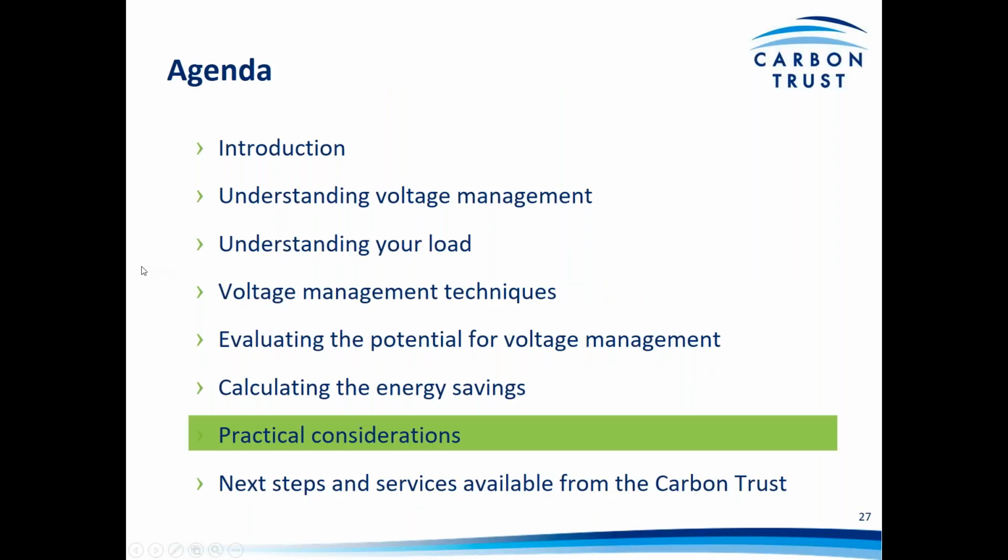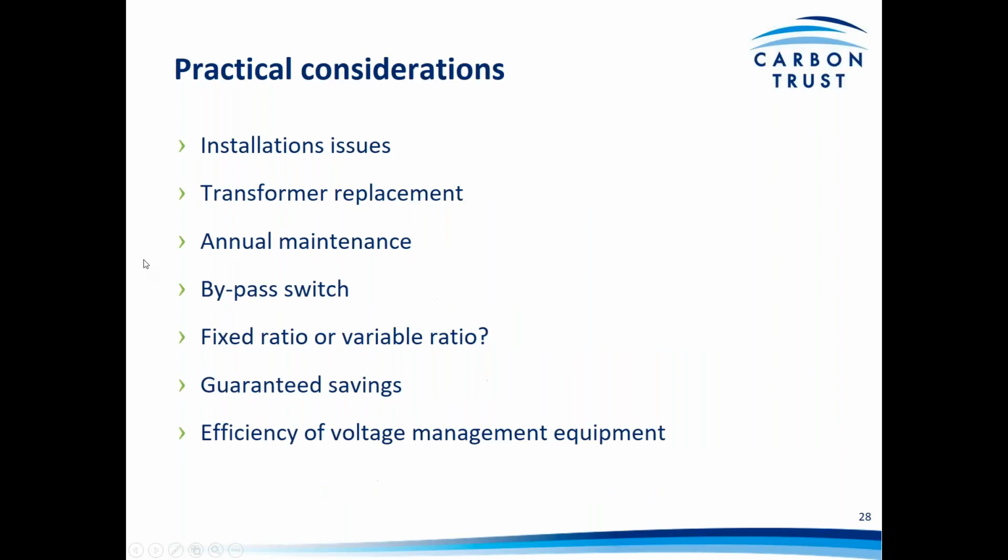Finally, on voltage management, just to have a brief look at some of the practical considerations. So just to run through these, installation issues. You'll need to consider, for example, how much space any new equipment will take up, where that is best to be located, as well as taking into account the need for additional cabling and controls, or just making sure that you've got a safe location for the equipment.